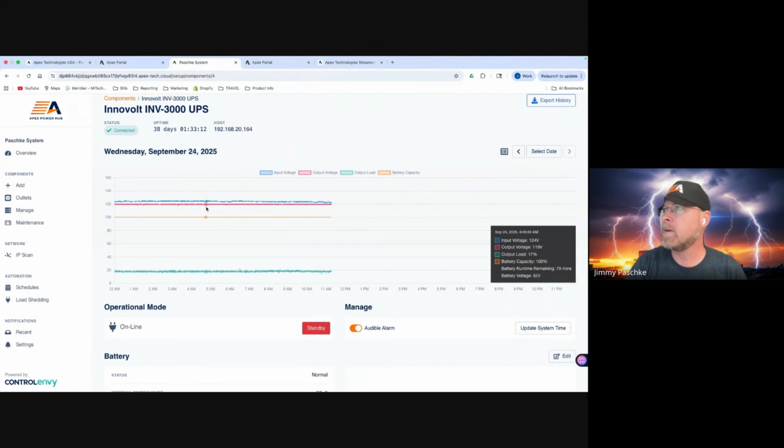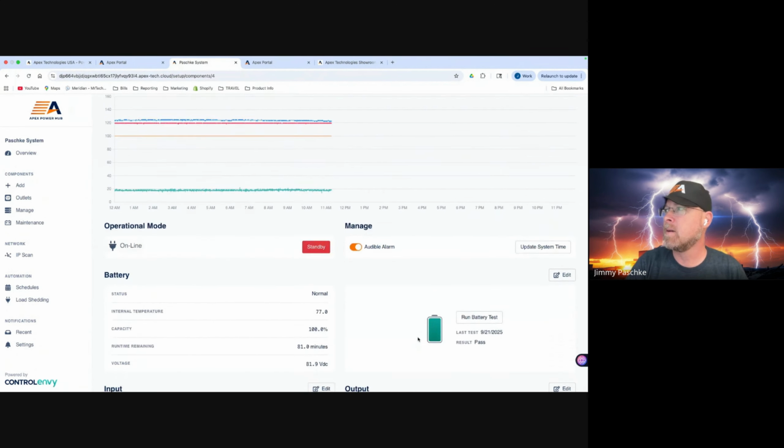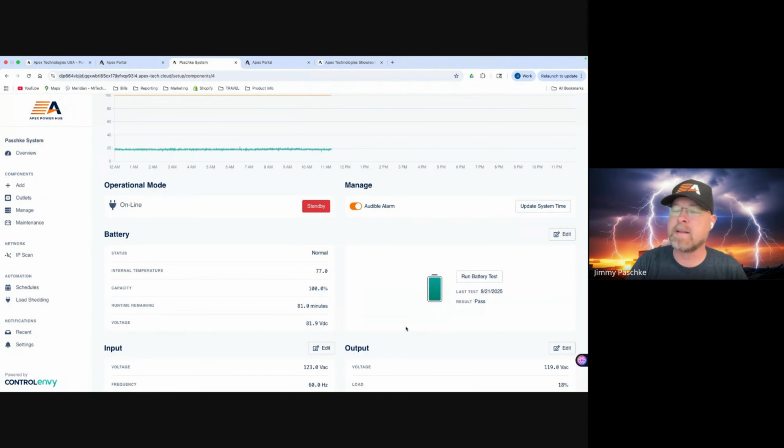My output's pretty standard. If the customer's calling us and they are having a power problem, it's likely that the UPS is beeping. If you want to stop the beep, just hit this mute button. This will basically mute the UPS. We could do this at setup, by the way. Just mute the UPS. The customer loves that it's helping them, and they freaking hate the beep. So just get rid of the beep entirely for eternity. The only time it will beep is if we have a catastrophic failure. But if it's just on battery pulling current because the power input is not acceptable, then it won't beep, which is good.